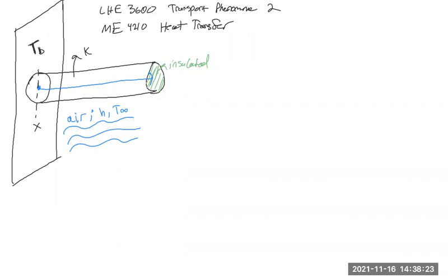because that's where heat is conducting from the base. If you imagine how the heat is trying to flow through this object, let's say it's really hot and the air is cold, so it's cooling down the fin, then you'd think that the heat is flowing down. It's not really flowing up, it's not spinning, and it's not going out radially. So generally, we say that the heat is flowing down the axis of your fin, and so it just turns into a 1D heat transfer problem.